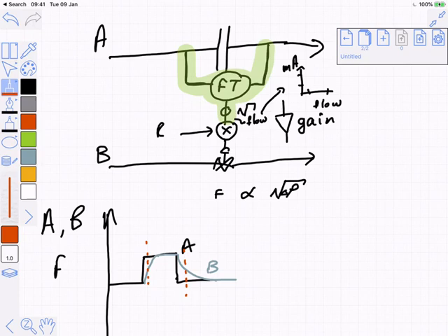Why? My catalyst has become poisoned. My flow rates are unreliable. The temperature and pressure that corresponded to those things in Aspen were calculated using models which weren't reliable even when we fit them to the data that they were used to get the models in the first place. Right? So the one thing we absolutely know is that the correct answer on site is not the one that comes out of Aspen.